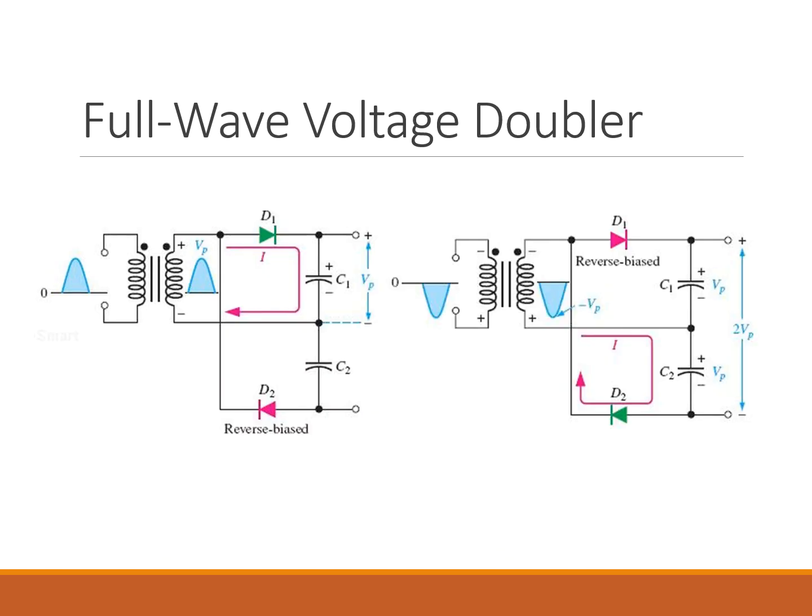Okay, so we've come to the end of our show here. So let's just recap. The last time we built a half wave voltage doubler. We're stepping it up to a more efficient version that uses both halves of the AC cycle. So we're going to introduce the full wave voltage doubler. And so you're asking, well, what is a full wave voltage doubler? This is a circuit that doubles the input peak voltage, just like the half wave version, but it charges both capacitors at the same time using the opposite half cycles of the AC waveform.